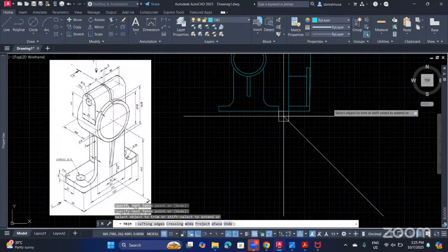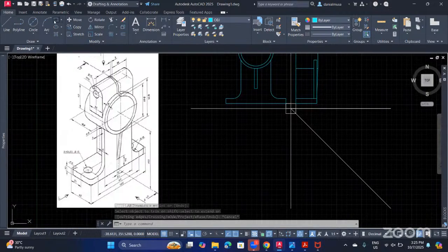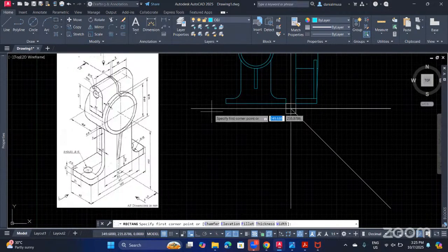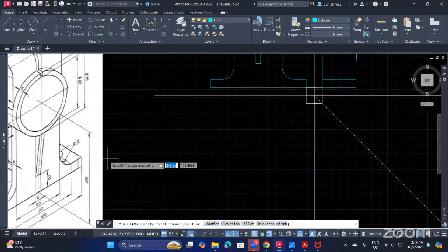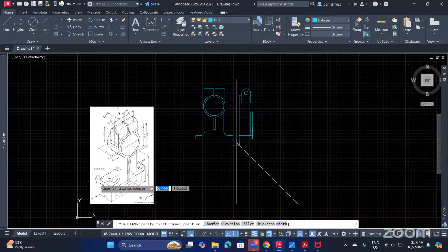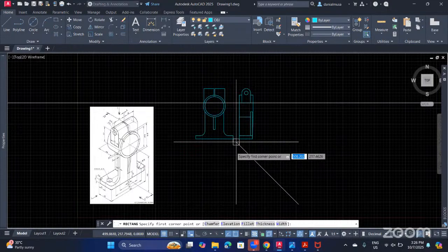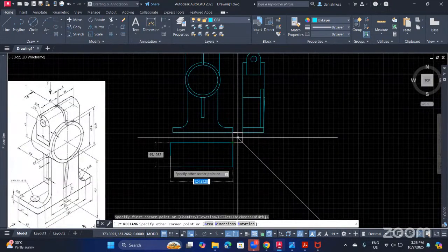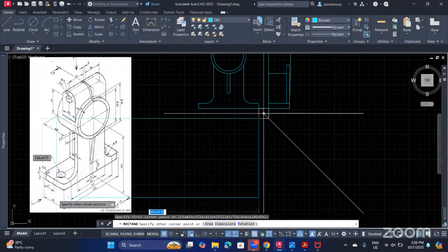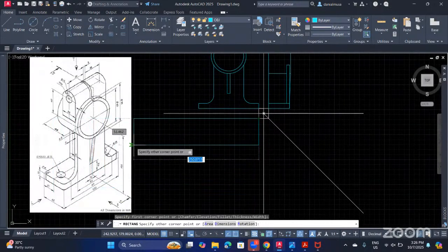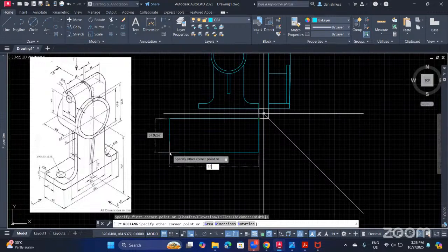After that, now we want to draw the top view already. So we just build the top view. Well, the side view we see here is just like this. The heading line we also draw later. So here we draw a rectangle. So it's 42 and 120. So we insert 120.